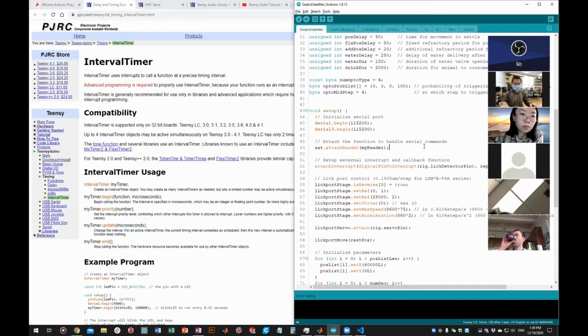A Teensy, for example, can have a 96 megahertz clock frequency. There are counters in the microprocessors. Every time the clock ticks, which is a very small fraction of time, like nanoseconds, the counters count 1. Then the clock ticks again, and it counts another 1.